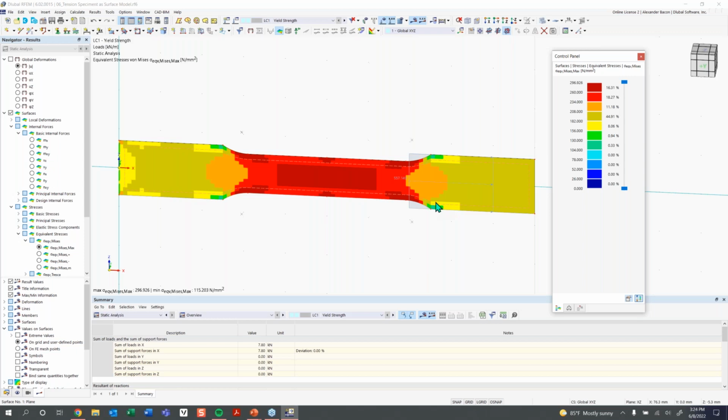So you may be thinking this is steel and it's an isotropic material, and this can happen if it exceeds that yield strength. This limit can't be exceeded. That's the yield strength. So these stresses wouldn't be shown realistically, and they wouldn't be passing 260 Newton per square millimeter. But we were getting stresses higher than that. So this is where we want to consider the material as a real nonlinear plastic material behavior.